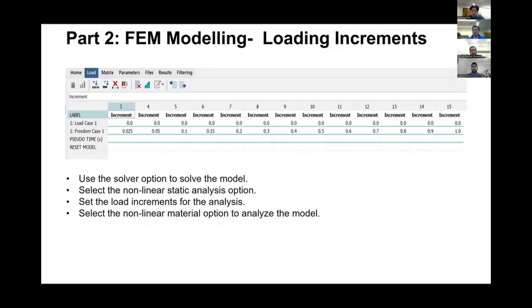Coming on to the next slide, where the load is being applied. The displacement is used, in which the displacement should be applied to the soil part interacting with the footing. In our model, the displacement is applied to the soil at the base of the footing. The displacement is usually divided into increments, and the division of increments of our model is taken in specified percentages, for example 0.1%, 0.5%, and goes up to 100%. The values of increment are as follows: 0.001, 0.005, moving on to 1.